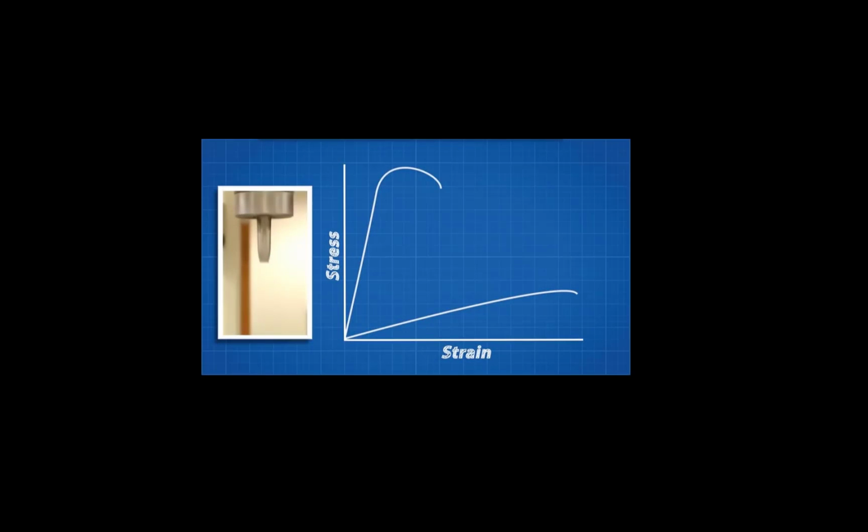So we've seen a stiff material and a flexible material. Now let's look at a material in between. This material can be described as tough and ductile. Tough simply means the material can absorb a lot of energy without breaking. The area under the graph here defines how much energy is absorbed. Ductile means it deforms under pressure. The two previous materials could also be considered ductile.